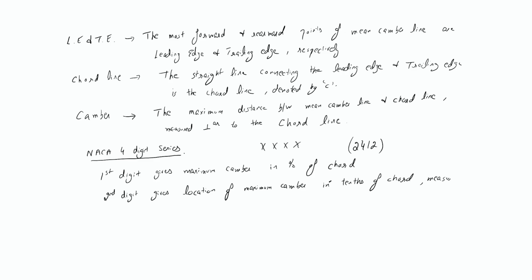Do not forget this: when measured from the leading edge. I am writing here leading edge as L.E. And the third and fourth digits give the maximum thickness in percentage of chord.